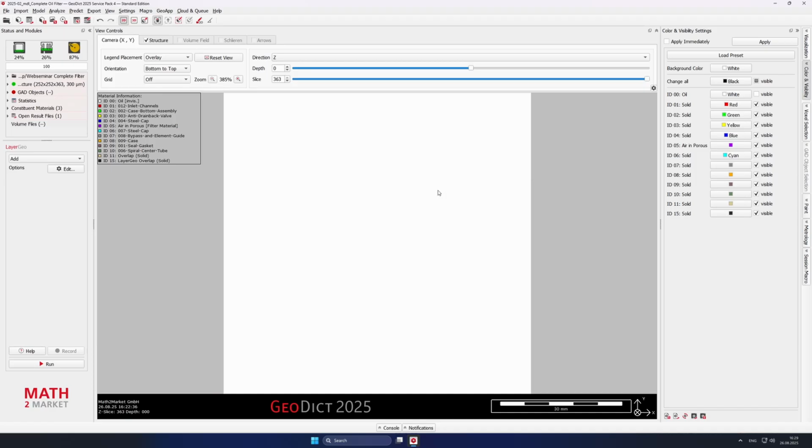The reason for that is pretty simple. The next steps will be to say this is the inlet, this is the outlet, and this is an outer solid, which stops the solver from actually flowing through a solid material. But if there's an empty slice at the beginning, then there's a connection between the outside and the inside of the structure. And if we then assign the whole component, it will be assigned to the wrong material.